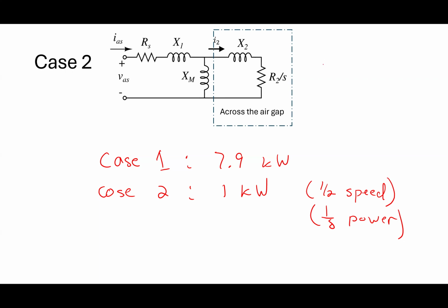What was true about the torque of the pump? It was some constant times omega squared, right? So what would be true about the mechanical power delivered? How do I always go from torque to power?